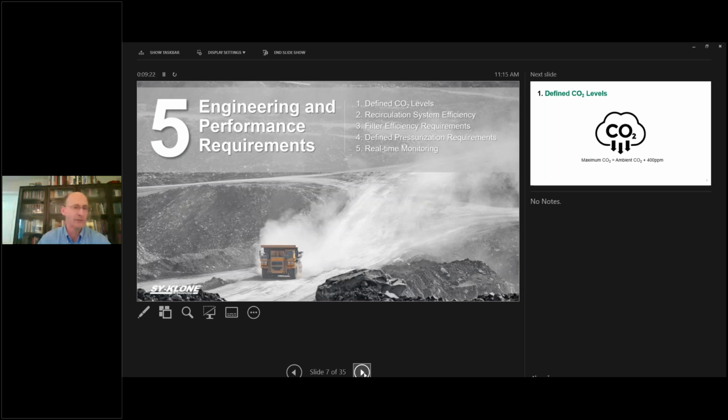So this is one of the benefits that we have here in addressing these two, the fresh and the recirculation airflow filtration. The next thing is maintaining cab pressurization, which simply means that we want to make sure that the cab is in a continuous state of positive pressurization. That allows the particles that come in the cab to be pushed out the cracks, but more importantly, because the airflow is always outward, it keeps the dust from coming in the cracks and contaminating the cab.